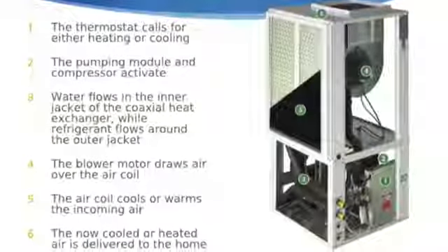The coaxial heat exchanger inside the unit is where the transfer from the water solution to the refrigerant will happen. We're going to take heat away from the refrigerant and add heat back to the refrigerant inside that coaxial heat exchanger.